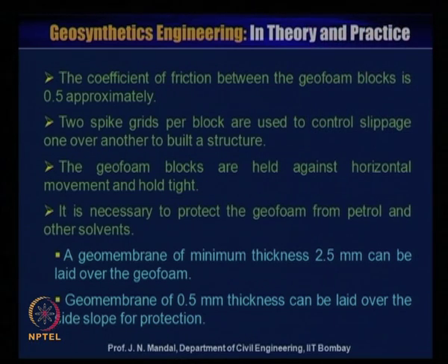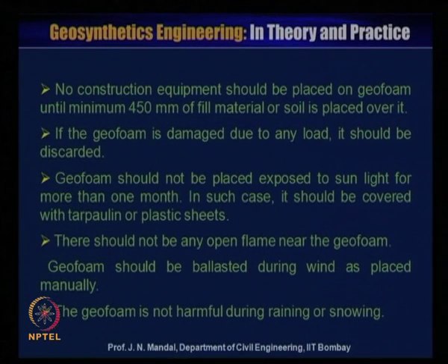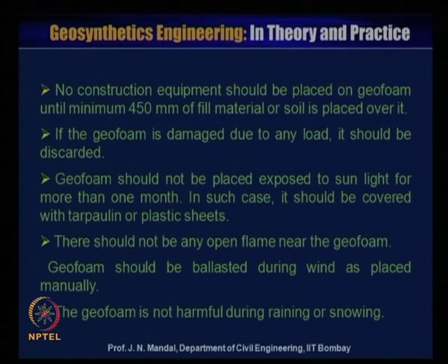So, when there is a possibility for any leakage from the petrol leakage, then you can provide a geomembrane material which can protect the geofoam. No construction equipment should be placed on geofoam until a minimum of 450 millimeter of fill material or soil is placed over it. If the geofoam is damaged due to any load, it should be discarded.